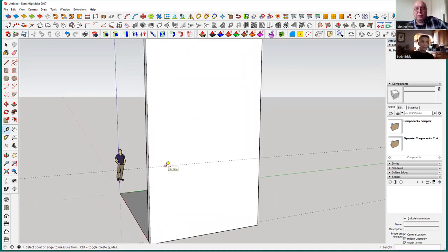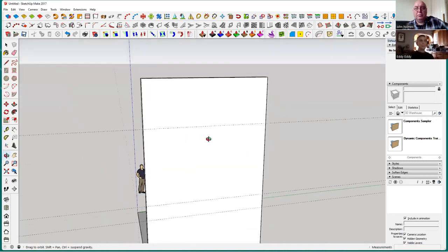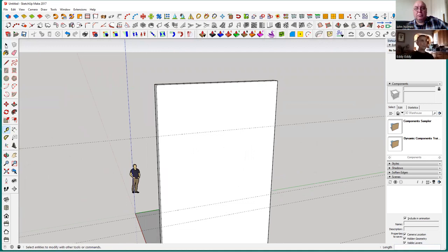Then we click again on that line and go up 0.5, which is 5 millimeters, enter, that'll be our floor. If we go up again 2.5, that'll be the ceiling of the first floor. So this top half here will be our roof.